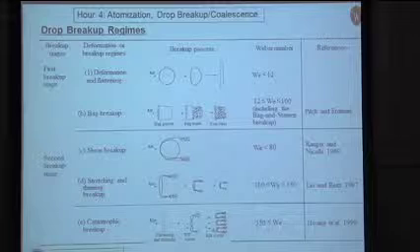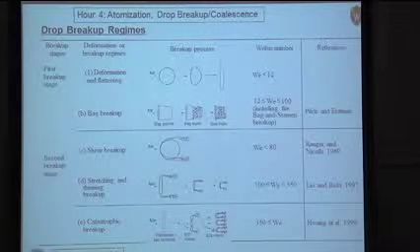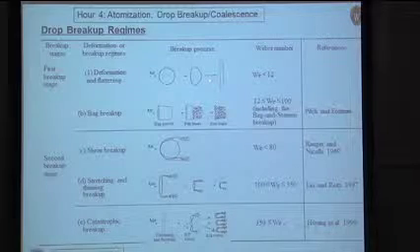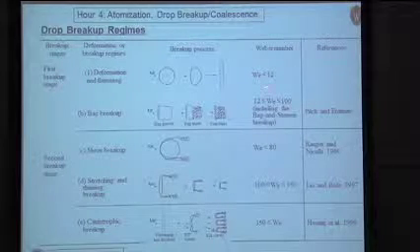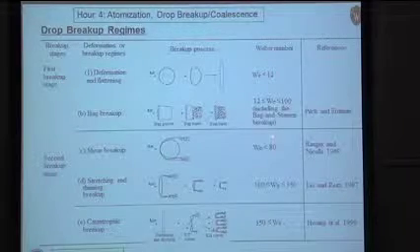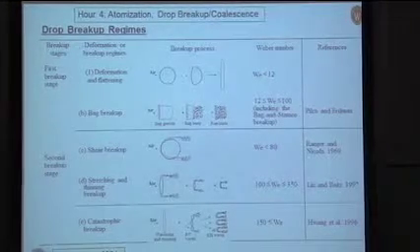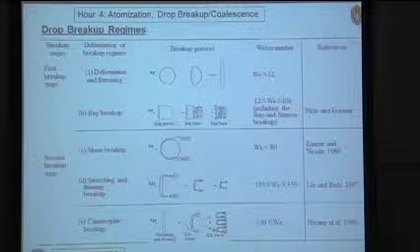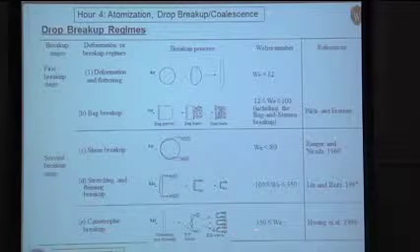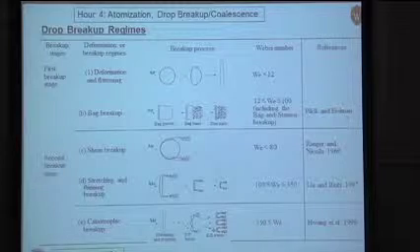So to kind of summarize droplet breakup phenomena, you can see we're going from the flattening of the droplets. This occurs at relatively low Weber numbers. These Weber numbers are based, I don't think I said it yet, on the gas density. And then eventually what we're calling catastrophic breakup for very high Weber numbers.